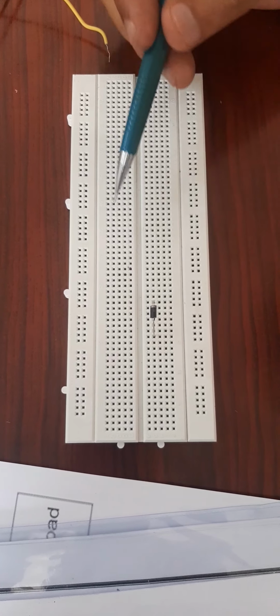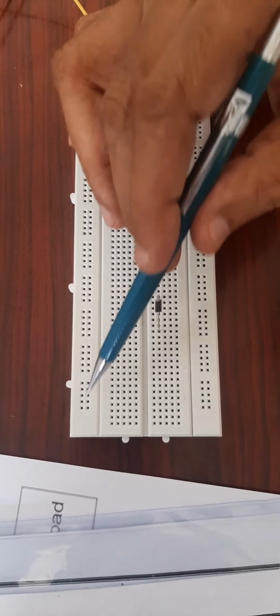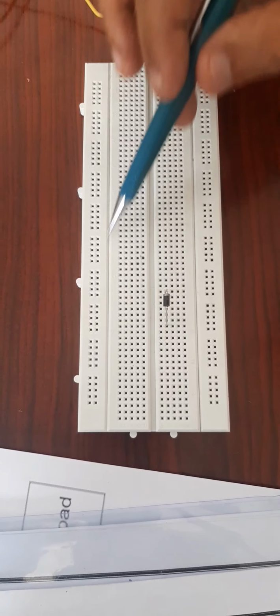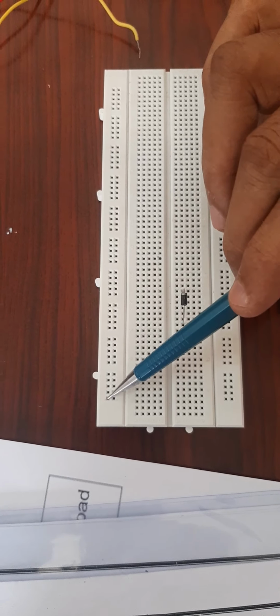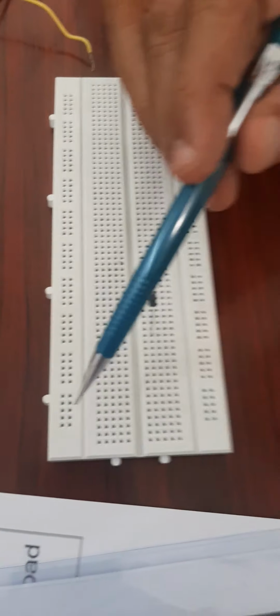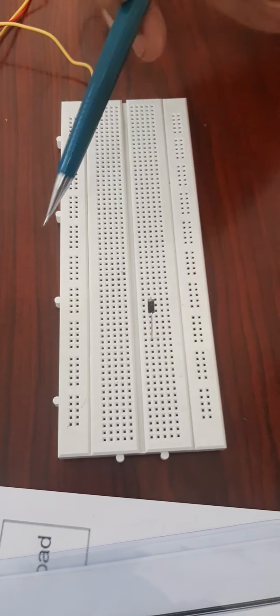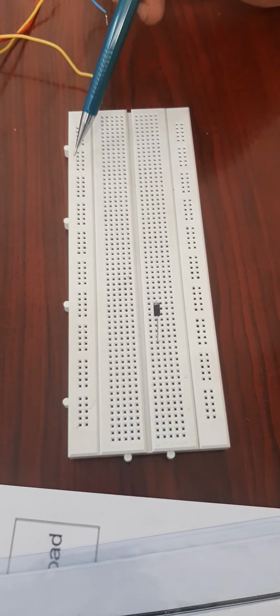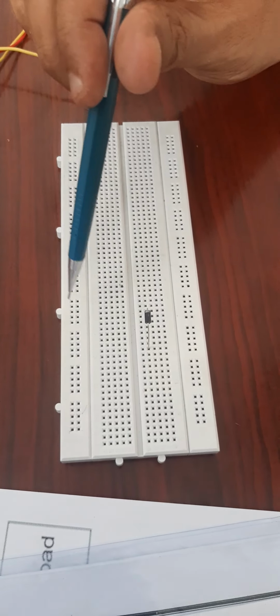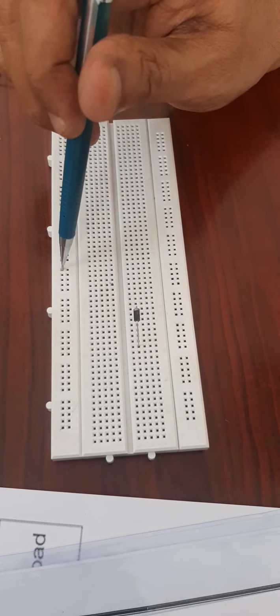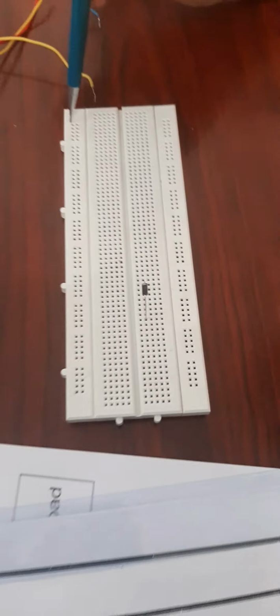You can see here there are 4 columns that have been mentioned here. The above one, this particular connectivity, is horizontal connectivity. You are having 2 rows here. If you connect here, you can get up to this one. So totally 4 sections are there in the above one. From here to here is one section, and here to here is the other section. All these particular holes are horizontally connected. Suppose you are going to connect a component here, you can get the connectivity up to this one. If you want to extend this one, you use a jumper here so that you can connect up to this one. Similarly, at the bottom of this one, this is also the same thing.